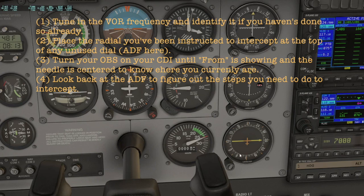I'll follow the rules from the previous slides about inbound and outbound radial interceptions based on where I'm at, what I need to do, and all I need to pretty much think about here is just to look at these directions. If I need to go this way, it's 210. If I need to go to the right, it's 300. If I need to go 45 degrees this way, well, it's right here for me. It's like 250. I'm sorry, 255. And all these directions are given to me, and I need to know where to turn before intercepting the next radial.